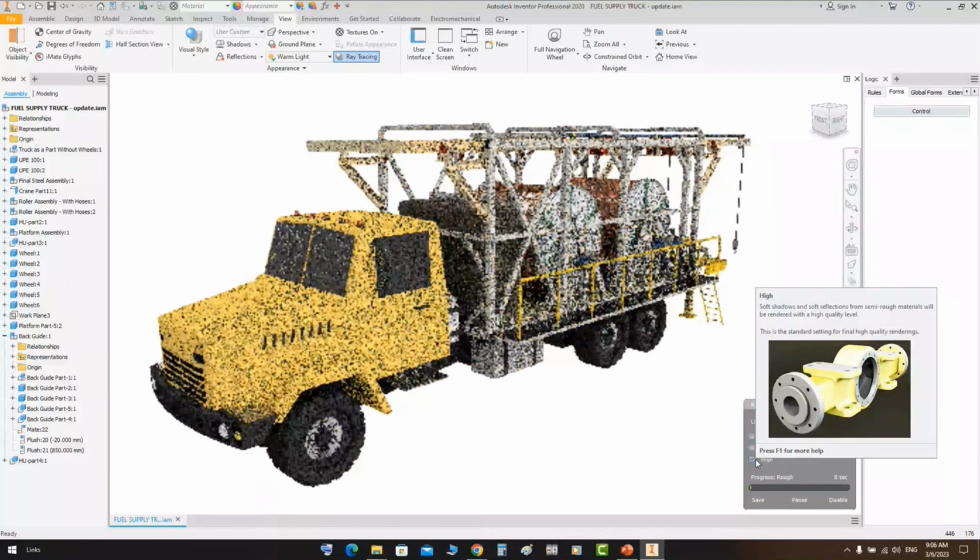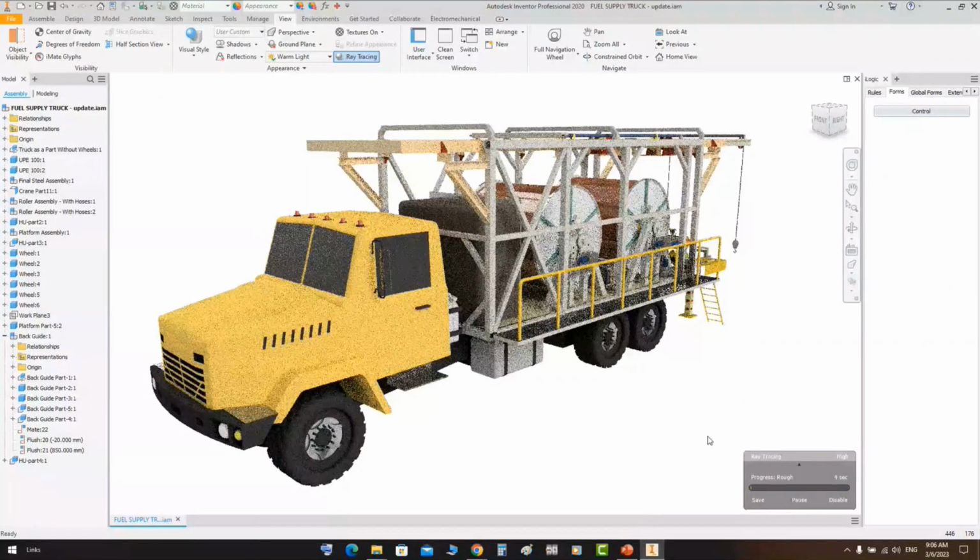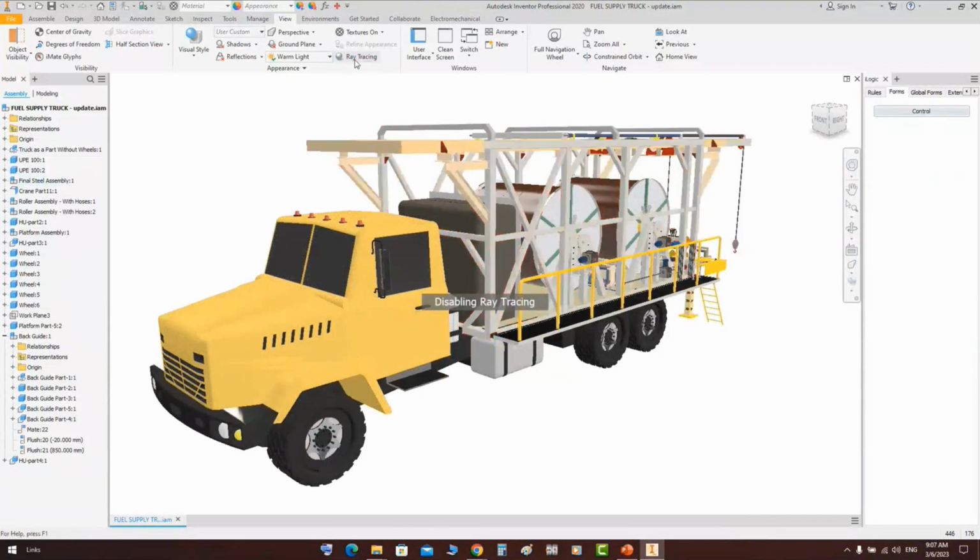As you can see, it takes time to make trials to render this image to make it look real. But we don't recommend using this if you are still working on your model, but you can use it if you would like to render the image at a certain time for your project. Now let's change the display. If you take a look, this button will appear only in case of realistic. So if we change it to shaded, this button will be disabled.